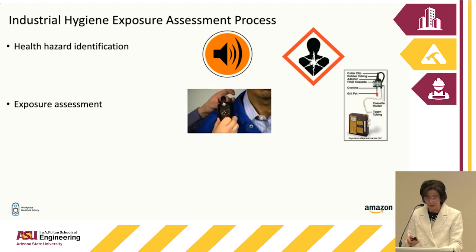So the industrial hygiene process is measured during normal operations after the equipment has been designed, procured, installed, and is qualified. That's when we come in with our little sampling equipment and we start to measure exposure. And we do it by looking at an 8-hour time-weighted average. We look at short-term exposure limits, which are 15-minute time-weighted averages, or ceiling concentrations. That might be like for carbon monoxide, for instance. You want to make sure that people don't have exposure to a high concentration that can cause immediate health effects.